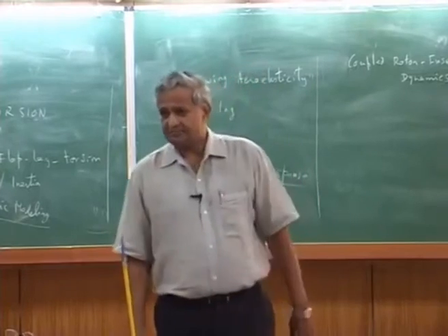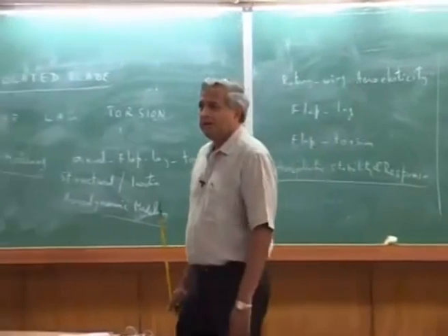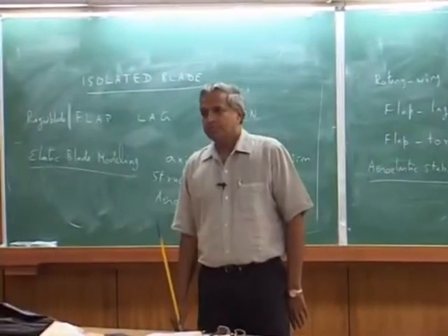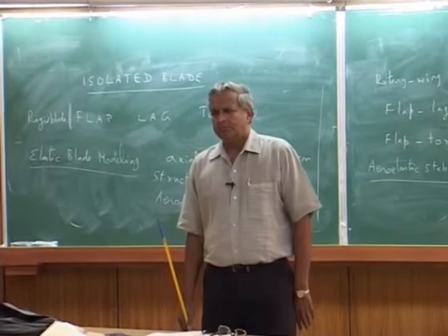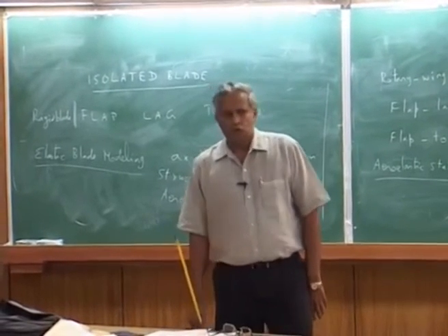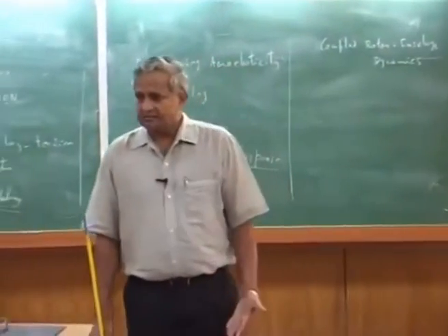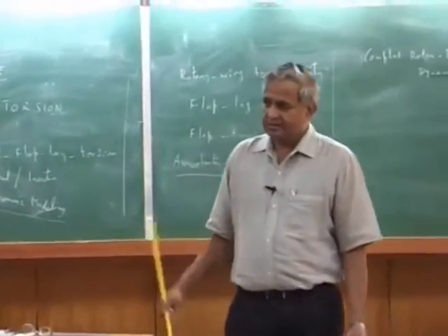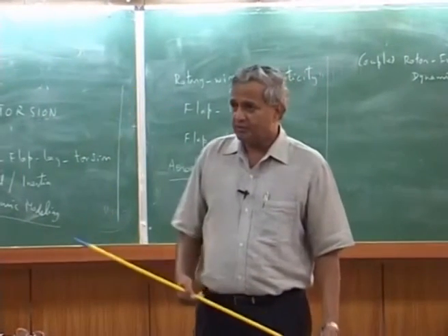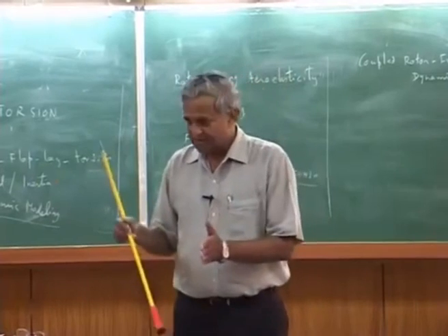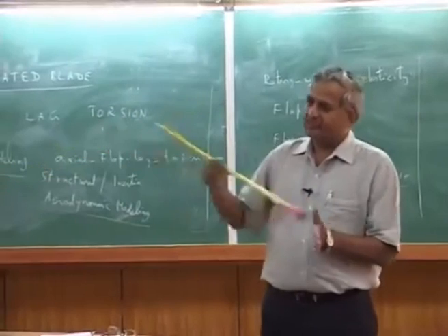That's all. So, one more note, sir. The blade hinge moment versus the EI, the blade stiffness. Blade stiffness would be far higher than the hinge moment which we are taking. Blade stiffness means what? Blade stiffness is EI. Yes, EI, sorry. EI in flap. Yeah, but EI is a variable. It's not uniform. See, in the aerodynamic section almost up to near the tip, it's a constant value.